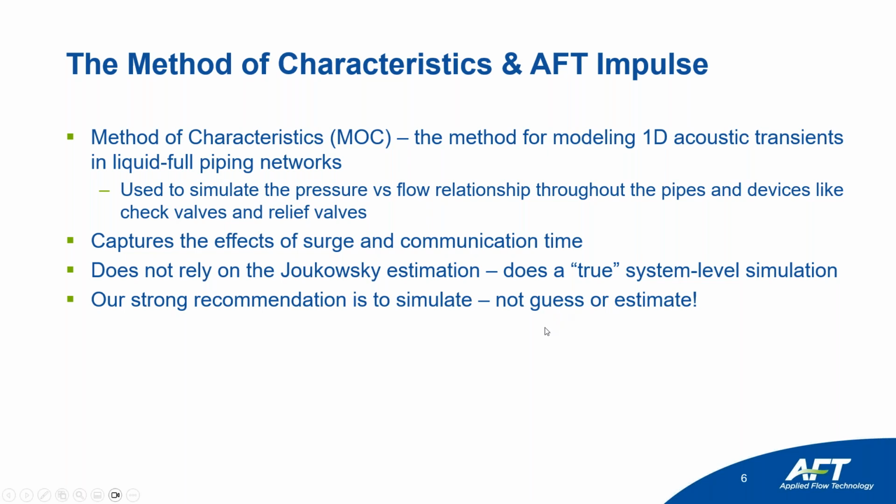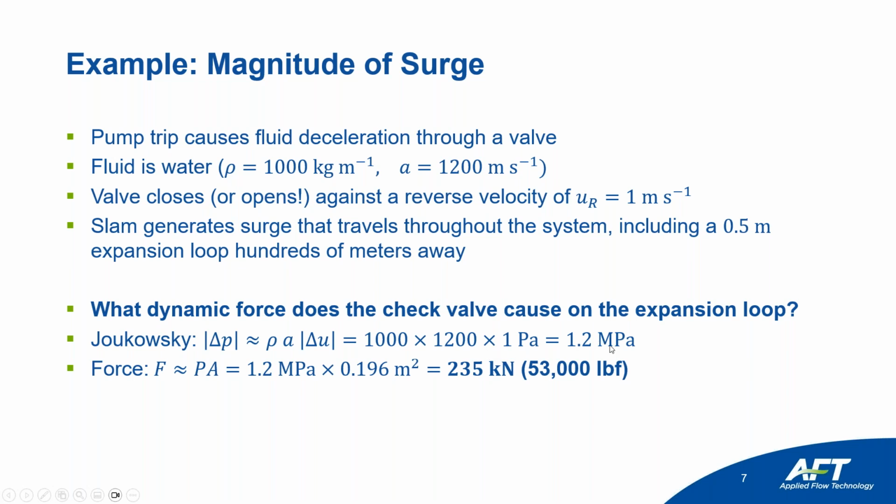So our recommendation always is to simulate things. Don't guess. Don't use the Joukowsky estimation and say you're good. It's not that hard to build a model, so go ahead and simulate it. An example of why this is important.